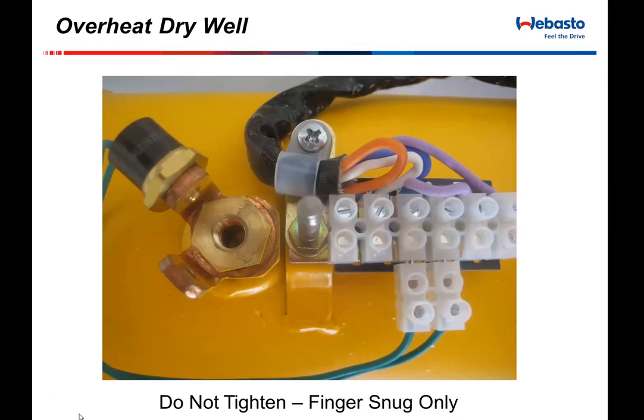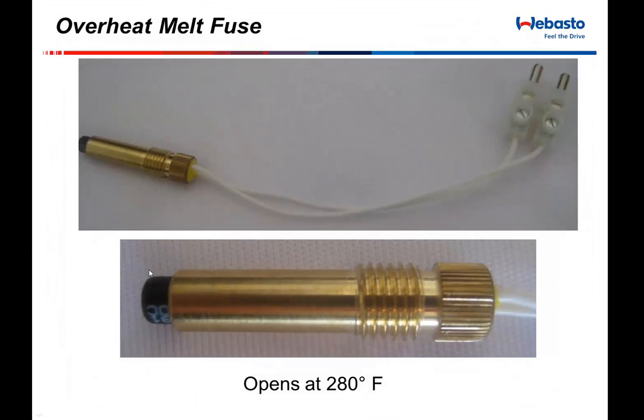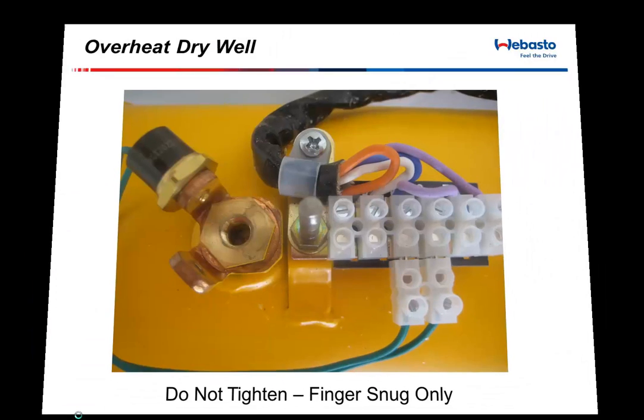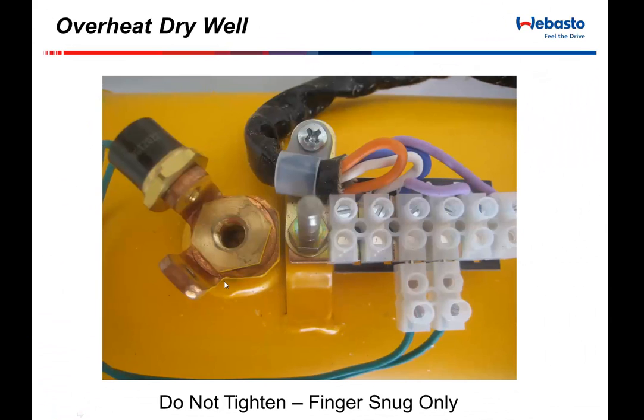And when you put that fuse in, don't tighten it down to a point that it's really, really snug. What can happen if you do that is this little waxy substance on the bottom of it will actually bottom out against the heat exchanger, and it will make it very, very sensitive. Get into a habit that when you put that thing in, you take it all the way to the bottom and then even back it off a full turn just to make sure that that little waxy substance is staying away from the top of the heat exchanger.